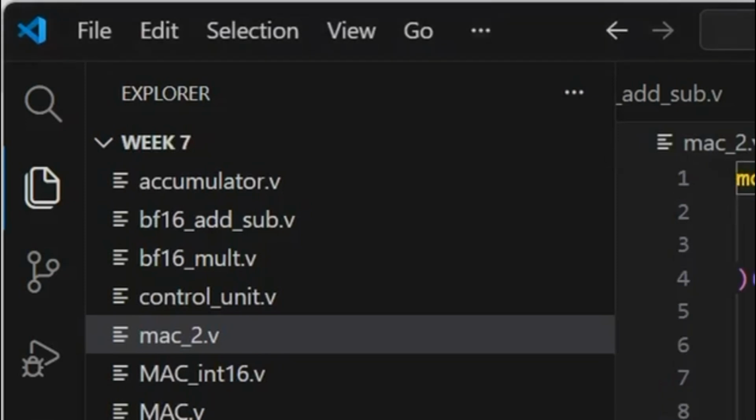There are two approaches to designing a MAC. The main critical issue with matrix multiplication is getting the inputs. You get an array of inputs and have to arrange it in a matrix and then do matrix multiplication with that. You can't really do anything else. So we either get a systolic array based input, structure it, and do MAC operations based upon that. Using that, we can get more of a dot product, which is not ideal for an AI application, it's more of a hardware accelerator point of view.